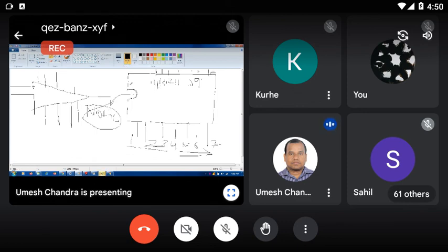In some cases, maybe the IC has no cutting position. Your IC is straight with one circle like this, and you consider this circle as the notch. Lower to the notch, you count pin number 1, left to right, and the upper side is right to left. Now, did all of you understand how to identify the IC pins? Yes, sir.